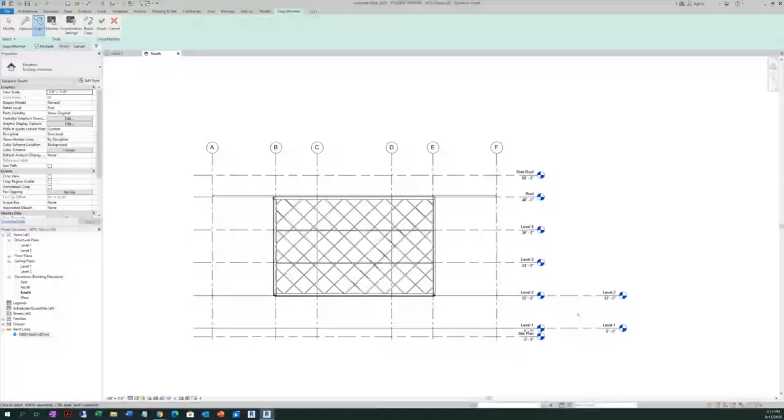But let's go copy. Still, we can delete it, but let's go copy. How are you going to do the whole thing in one shot? You come from your upper right section, click, and do a kind of crossing window selection, right?